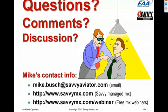So to me, for a simple airplane with minimum redundancy, it's more important to be able to monitor what's going on inside those cylinders than it is for a sophisticated airplane like mine that's got oodles and gobs of redundancy. So absolutely, the first thing I would do is add an engine monitor. You don't need anything fancy. A JPI EDM 700 or EDM 730 would do fine. I assure you that it will pay for itself in a year in terms of reduced maintenance costs, because it makes it so easy to diagnose problems that are very hard to diagnose without an engine monitor. So that's definitely the first thing I would recommend.